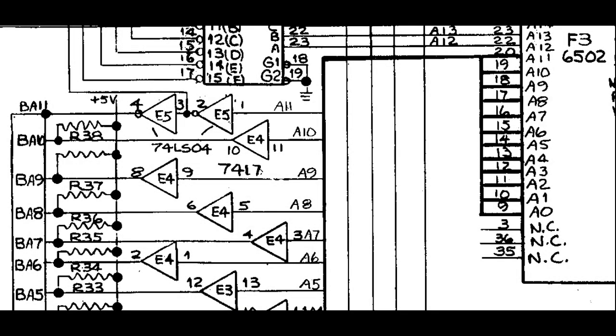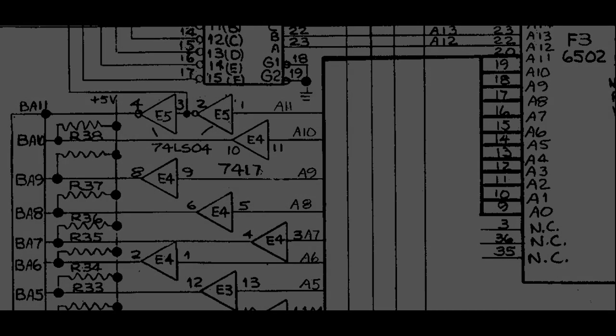As a practical demonstration of the NOP socket, I'll try it on my Commodore PET 2001 motherboard, and we see here a little part of the schematic of this board, where we can see some of the address lines going through buffers, A11, A10, A9, A8, A7, and so on. And so we will check that we have input signals on these buffers and output on the other side.